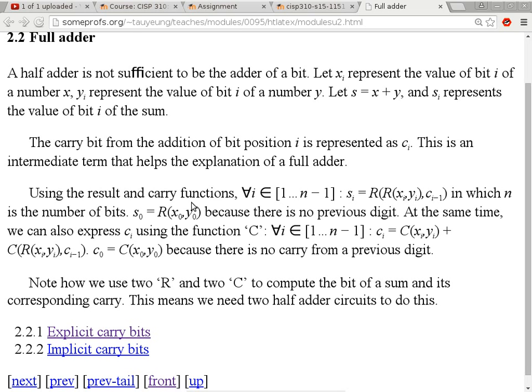It will take time to turn on or turn off this transistor. It will also take time to turn on or turn off this transistor. That amount of time depends on the area of the junction, which basically forms a small capacitor. So you have to charge or discharge the capacitor in order to turn on or turn off a transistor. So there's a delay. Is that okay?